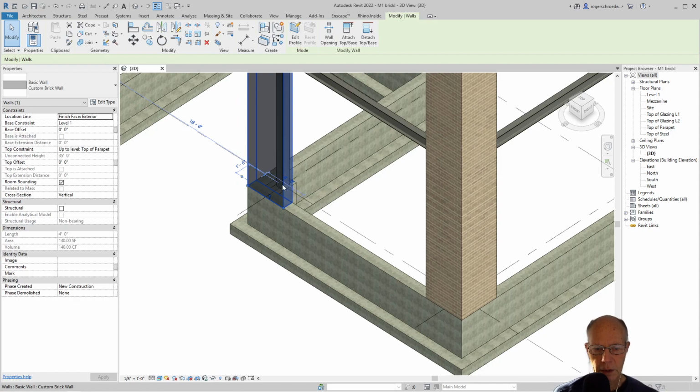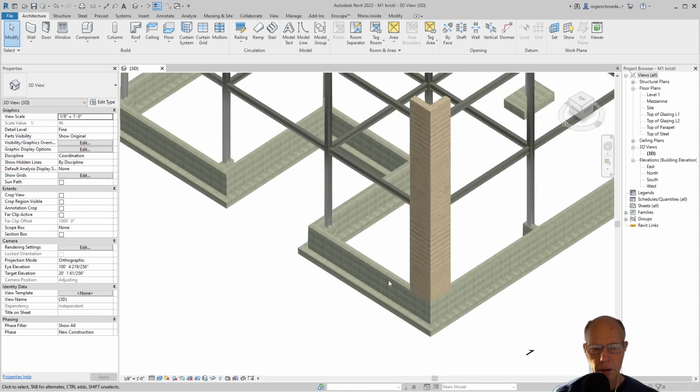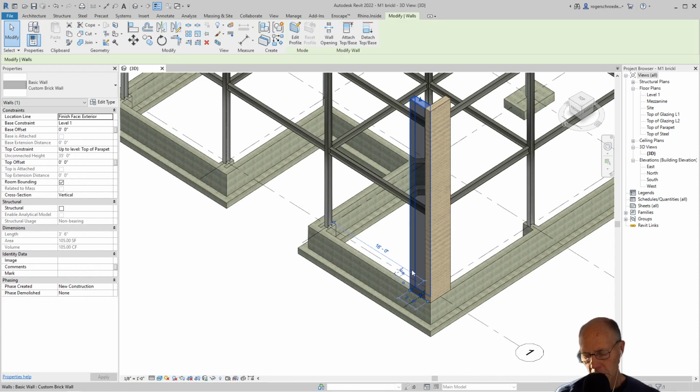But like I said, I'm going to delete this because we know that there's symmetry here. This edge to this steel is 20 foot on center, so everything is symmetrical. So this little section of corner will be duplicated here, and then this whole unit will get duplicated over there. So we can use some of the power of our duplicating and modeling commands.